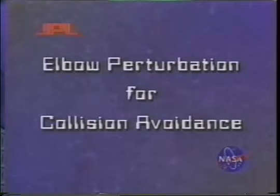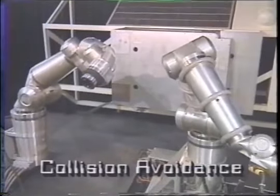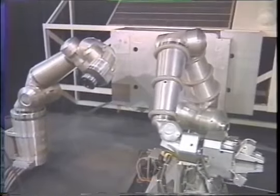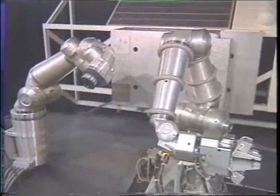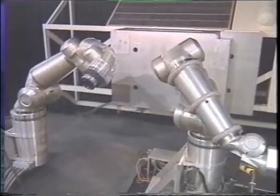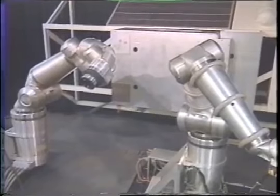In this experiment, we demonstrate reconfiguration of the arm to avoid an impending collision. When the elbow comes close to an obstacle, in this case the left arm, then the dexterity of the arm allows the collision avoidance software to rotate the elbow away from the obstacle without perturbing the commanded position and orientation of the end effector.